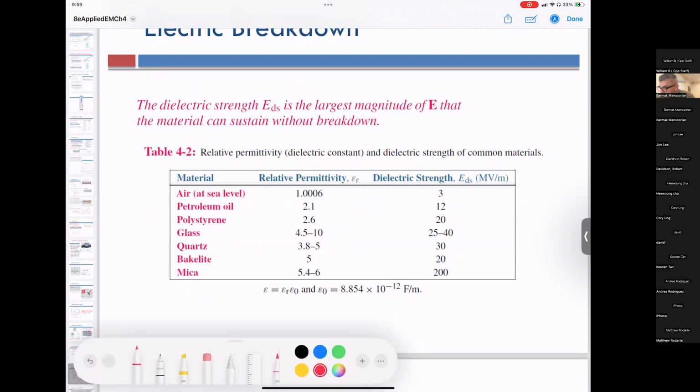Now, electric breakdown is one of those things where the electric field for breakdown is always in megavolts per something, so it seems like a gigantic number that you'd never run across in the real world. But the problem is this "over meter" thing. It's megavolts over meter, but the dielectrics in your capacitors are never a millimeter thick.